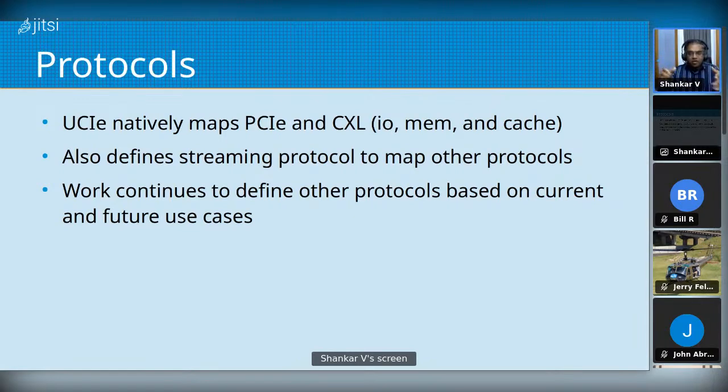So there's this open thing. They call them bunch of wires or sea of wires, different terminology. And that one, the protocol definition is left to the vendor to define. So it still allows, if AMD or any other company were to define a custom protocol for two chiplets that the same vendor makes, and they think that going over one of these other protocols is going to be less efficient, and they can customize a protocol for their particular application,